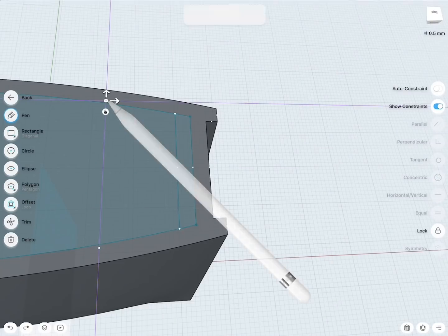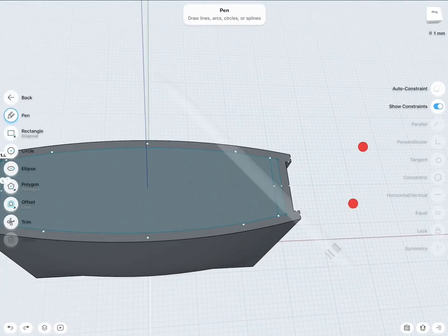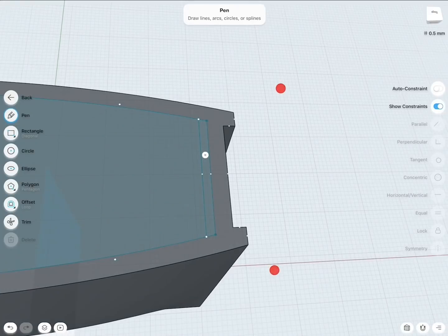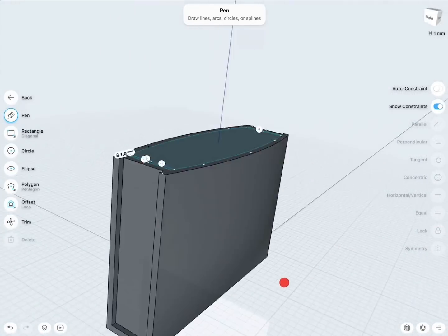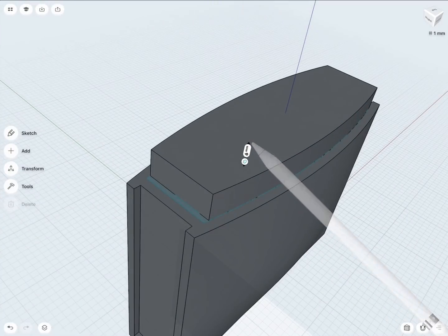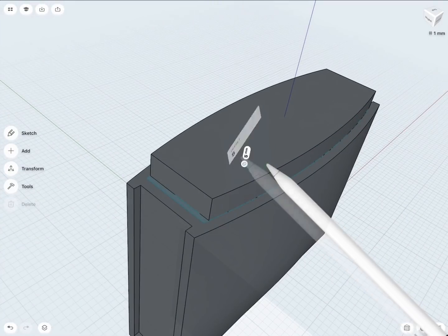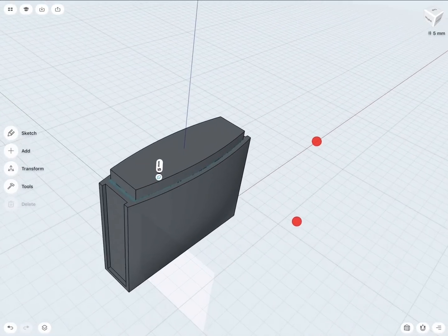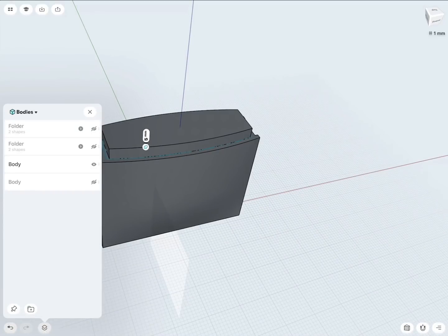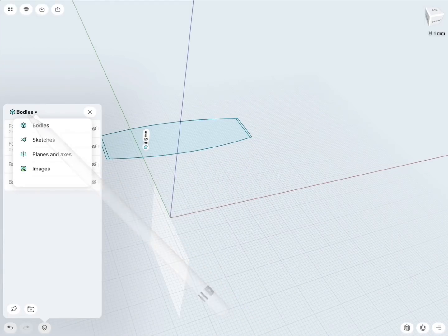Very good. And I select this line and say equal. There you see exactly the same process. Can then select this part, extrude this up, 5 millimeters. Very nice. So we would like to have the spray bottle, or not spray bottle, the spray element. This one I will hide for the moment.